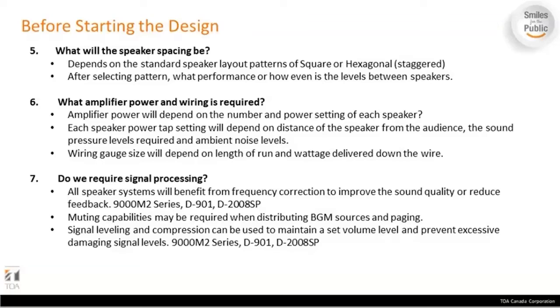So the amplification part is very, very important, because that is what is going to drive the speakers and give you output, right? So by rule of thumb, what we usually prefer is 20%. We leave a margin of 20%. So you should try to keep a buffer, right? So if you have 240 watts of speakers in totality, you should have a safe margin of amplification. Don't just go with a 240 watt amplifier with 240 watt speakers, right? So it's better to always keep 20% more. In this case, it would be roughly 40%. Go for a 300 watt amplifier for 240 watt speakers, right?